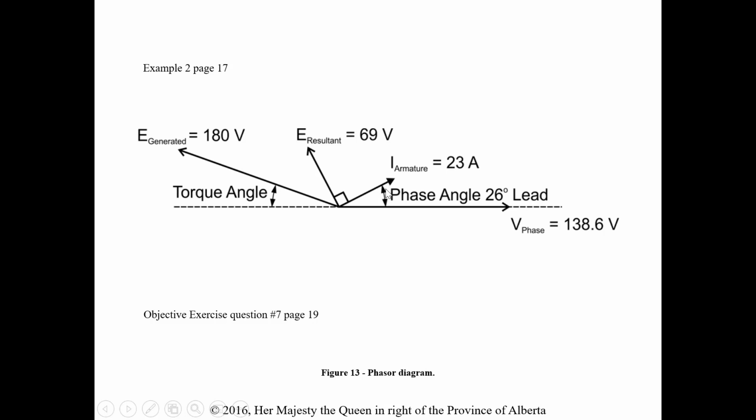So what that does is it pulls the phase current off of the 0 reference and gets us into a lead. By changing the torque angle, we can change where the current sits too. So by changing the torque angle, we've actually got this motor into a leading power factor, which we usually wouldn't be able to see in a squirrel cage induction motor.